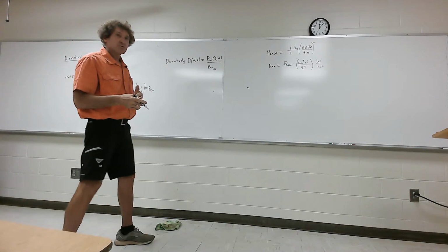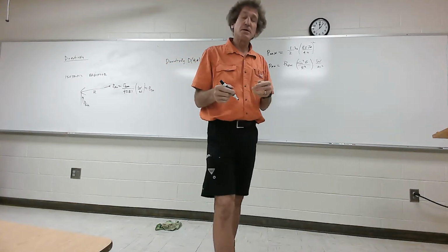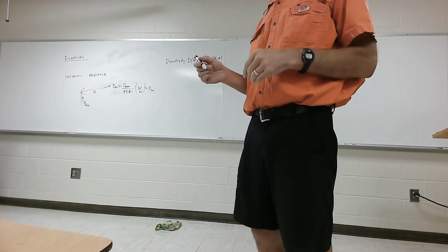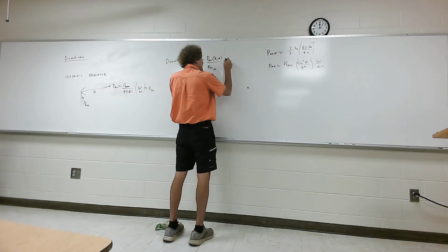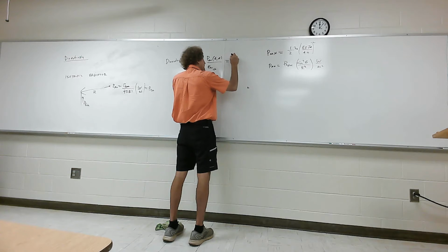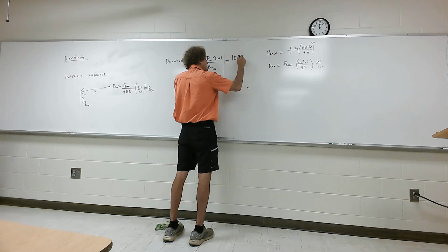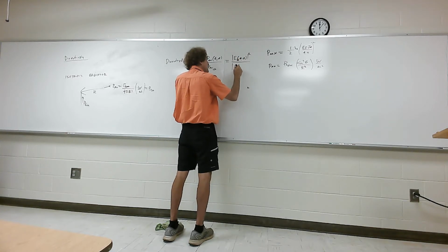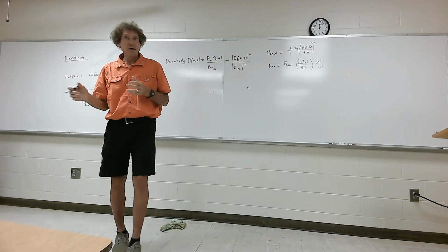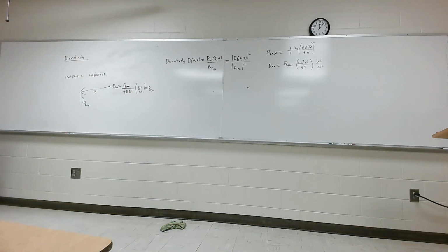We can translate that in terms of the electric field, because the electric field is related to the average power density by a squared operator. You have to square it. So this is also equal to the magnitude of the E field from your antenna, squared, over the magnitude of the E field from an isotropic radiator squared at that same range. So it's really telling you how much better it is than something that doesn't focus. Do y'all follow me?